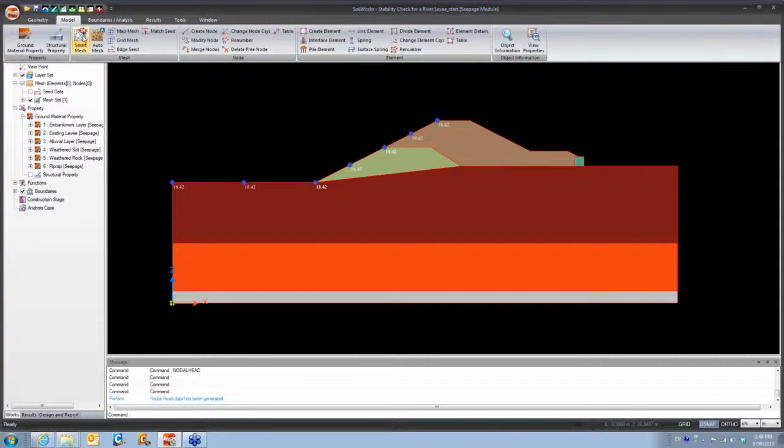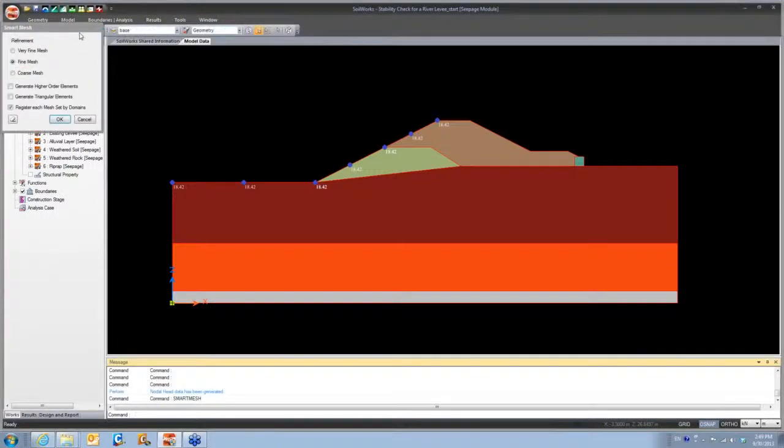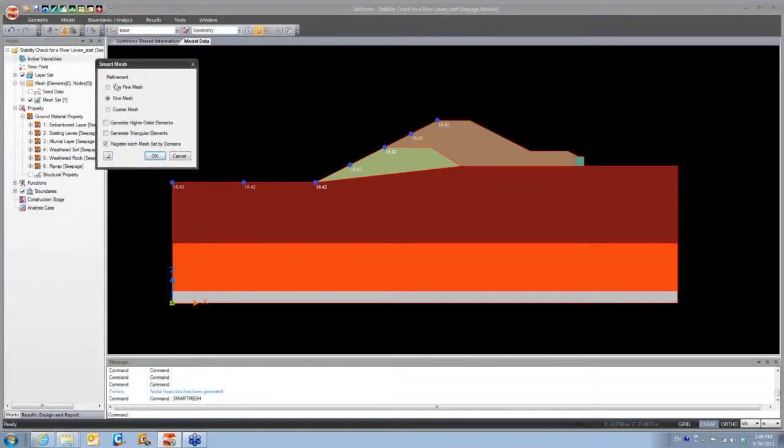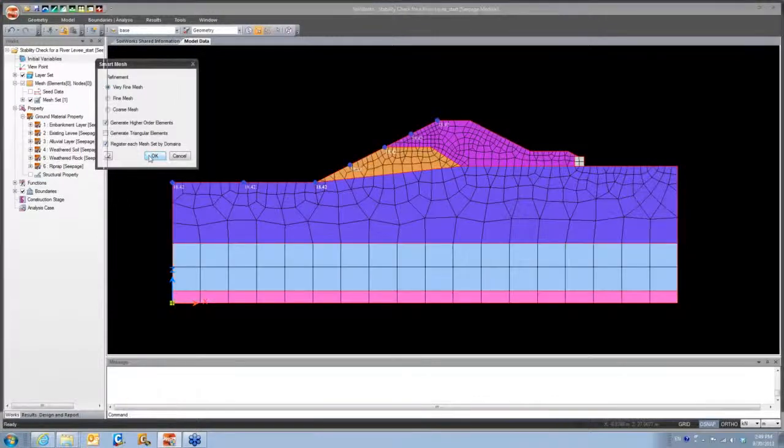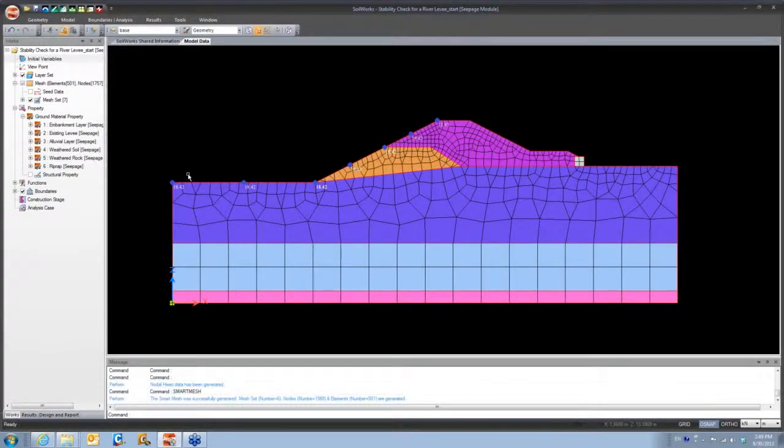Oh yeah, absolutely. Okay. So you should see the meshing options now. Here under the mesh tab, you can see all the different options that you have for creating your meshing. The ones to the right, for example, map mesh, grid mesh, are just manual options for creating your mesh. But if you want to create a mesh very quickly and very efficiently, you just select Smart Mesh, and you select your parameters. Okay, so I just created my meshing.